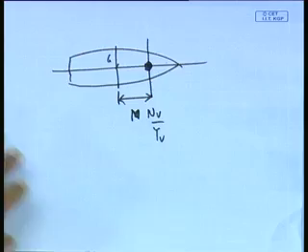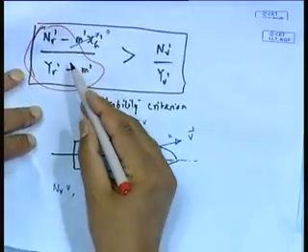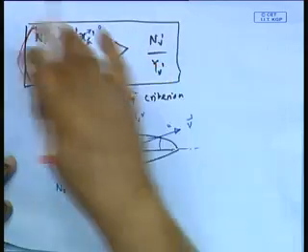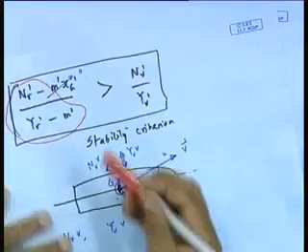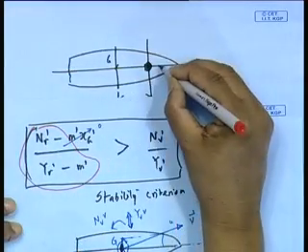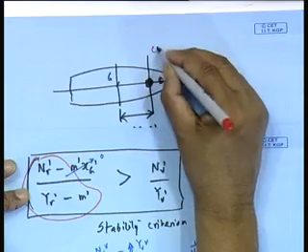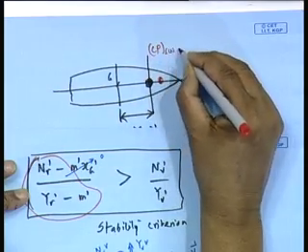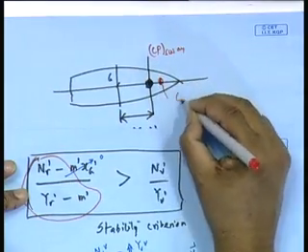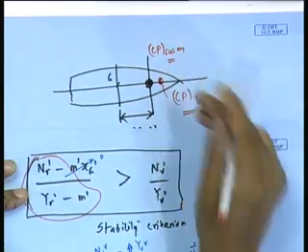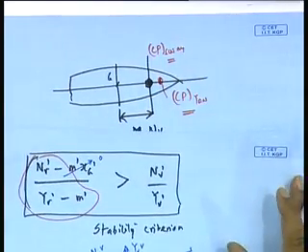Whereas this other term would be the distance where the moment would act if there was only yaw motion. So what the criteria tells is that if I call this Cp sway, and this Cp yaw, the center of pressure of pure yaw must be ahead of this. That is what it says.